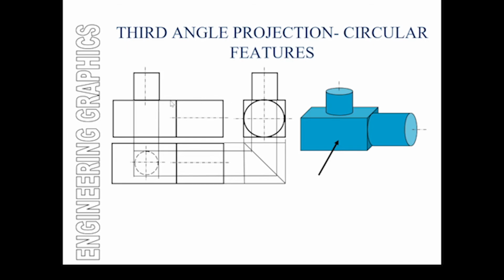But if I were to produce these three views, that should be enough information for anybody to understand what that is, obviously along with the dimensions. So if I see a rectangle here with a center line running through it, I know it's not a rectangle, it's a cylinder. Same story applies here. We have a cylinder, and very clearly we are looking at a circle straight on, so we are expected to draw a crosshair-like pattern where we indicate both axes like so, and all of these lines tally up. So that's something you need to bear in mind to be able to produce a meaningful technical drawing.